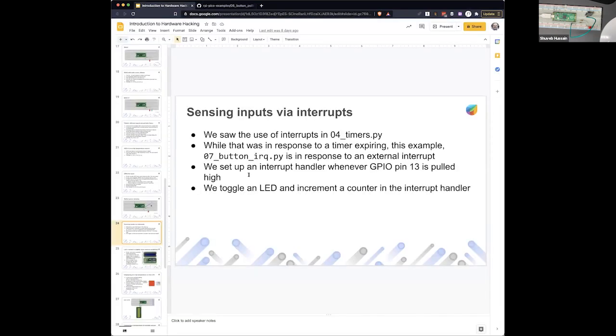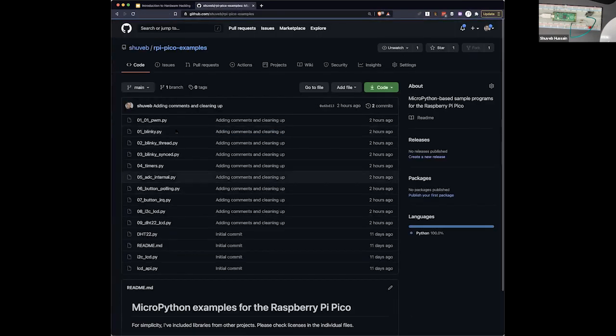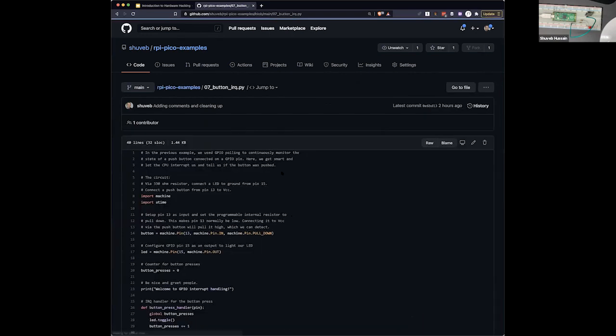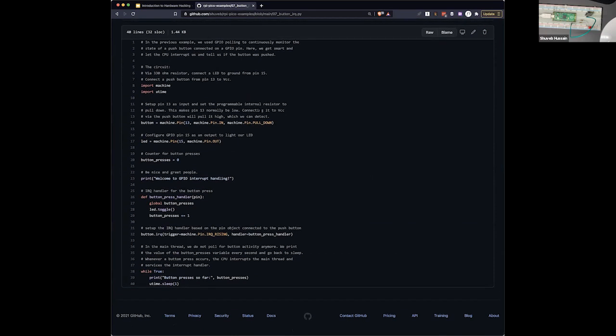So you can definitely do something better. You can set up an interrupt on the GPIO pin, and there's a much better way to handle this. This is the exact same program, but we are adding one extra statement here. We are saying that whenever this pin goes high, you simply call a callback. And then in the while loop, you can do whatever you want. That's the whole idea. In the callback, or the interrupt handler to be precise, we toggle the LED.